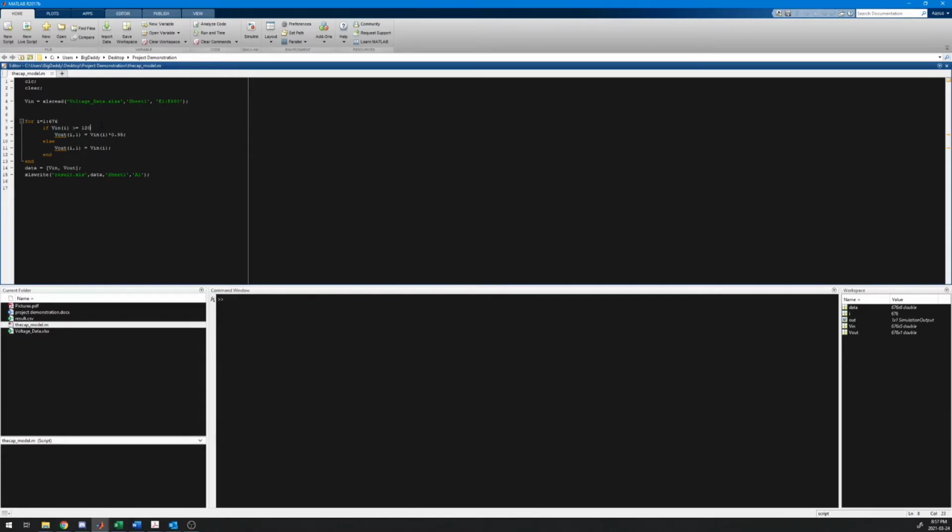If the voltage is above 120 volts, that is fed through a step-down transformer to reduce the voltage to the desired level. This was done to mimic the voltage reduction logic that the CVR Smart Plug implementation creates. Since our transformer is customized with a ratio of 1 to 0.95, that is the factor we're going to use to decrease the voltage. We run this program and we generate the Excel file results.